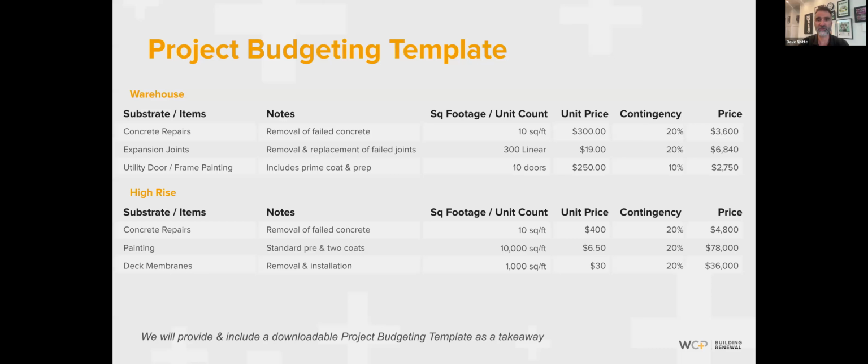Service life of an expansion joint, boots on the ground, is 8 years. The manufacturers will tell you longer, and certainly owners want it to stretch longer, but it's 8 years. So if you're walking around your warehouses and you see any of the expansion joints delaminating from the side, or they're very soft, or you see cracks and checks throughout them, it's time to replace them.